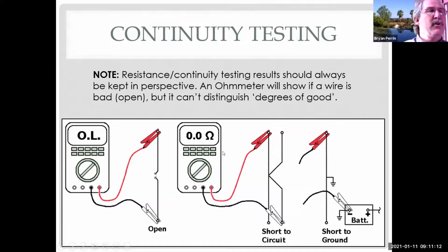Like I said, occasionally you'll use an ohm meter to test a component on the bench. But if it's an actuator, why don't I just power it up and see if it works instead of measuring the resistance? Right? So why should I use resistance to infer that it should work when I can test it to see if it actually does work?